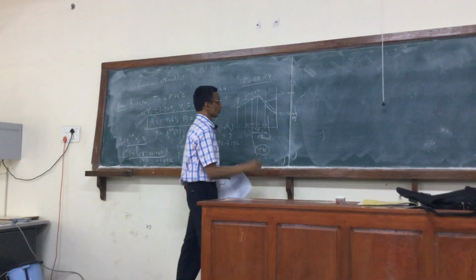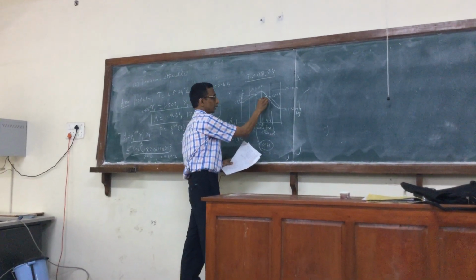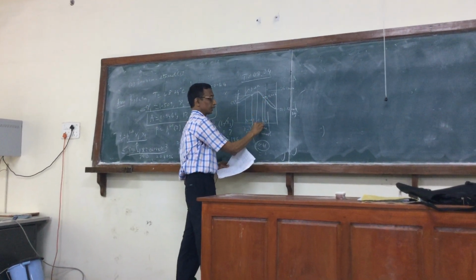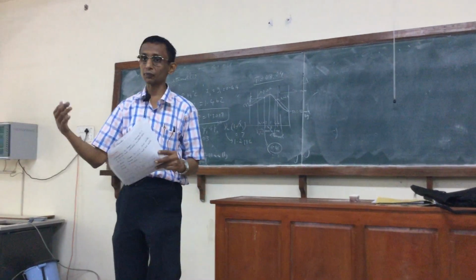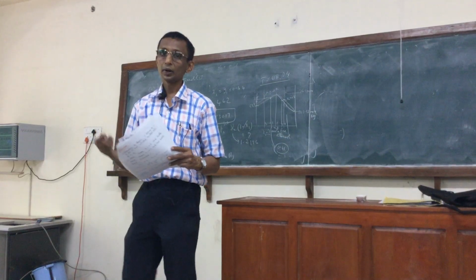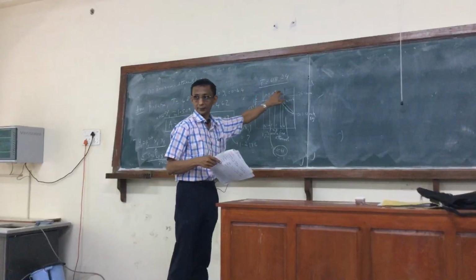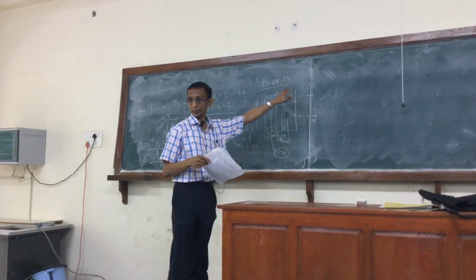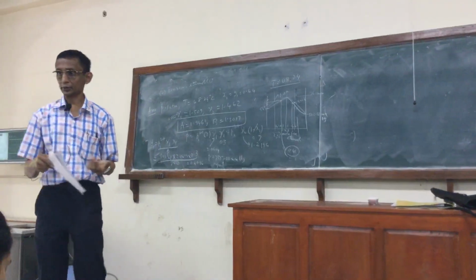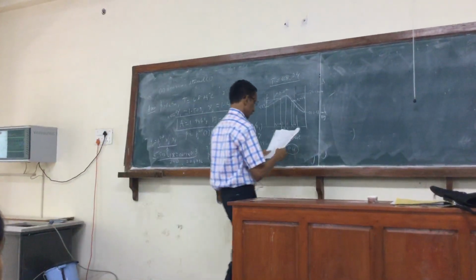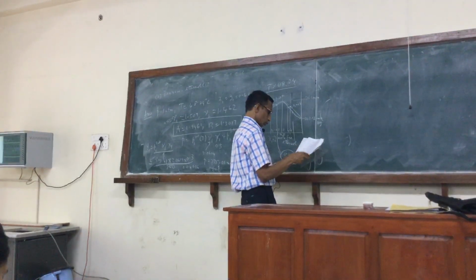Then I can calculate y1, which we expect to be less than x1 because it's to the right of the azeotrope, both on the Txy diagram and the Pxy diagram. To the left of the azeotrope we have y greater than x, and to the right it would be less than x when we have a minimum-boiling azeotrope. We can easily verify that with the calculations.